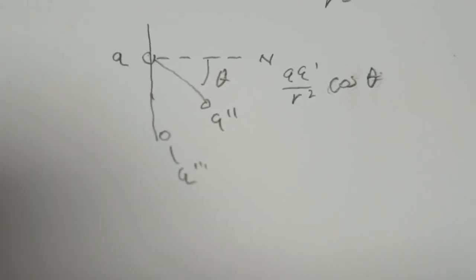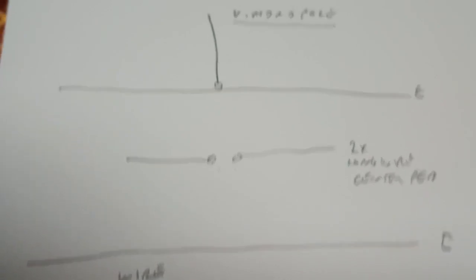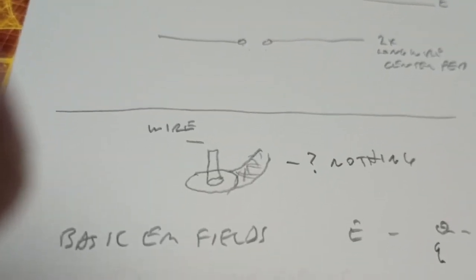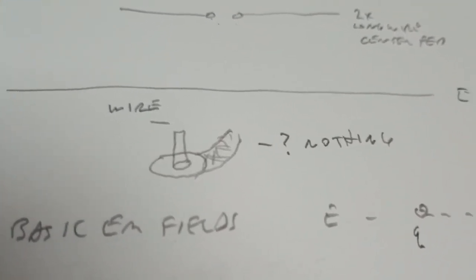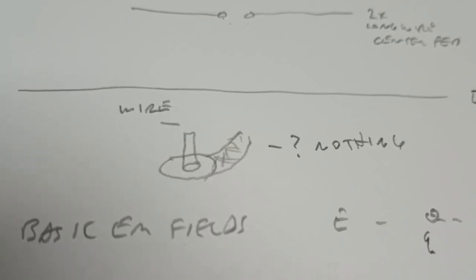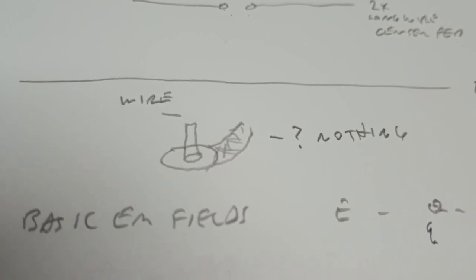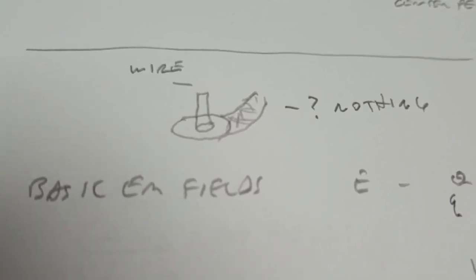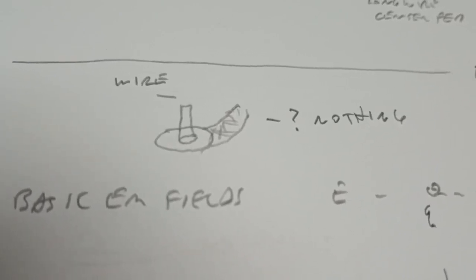This bottom diagram is all about what vertical monopoles are about. The problem with the vertical monopole and the end fed is that here's the end of the transmission line. There's a potential on the end of the line. Let's say it's an RF AC, but we stop time and it's at some voltage, some potential. There'll be field lines in the dielectric space in that transmission line. There'll be field lines between those wires exiting, but that's it.